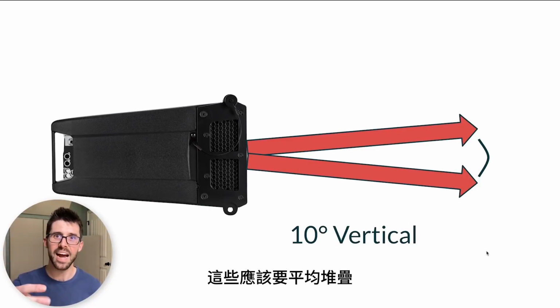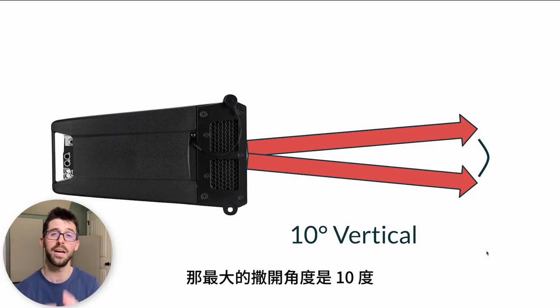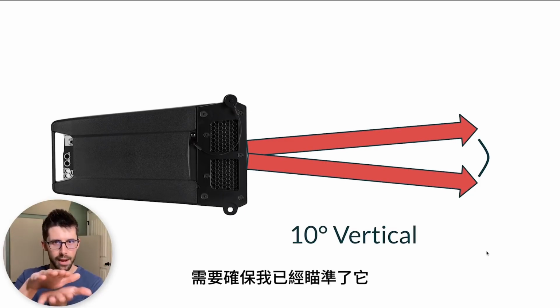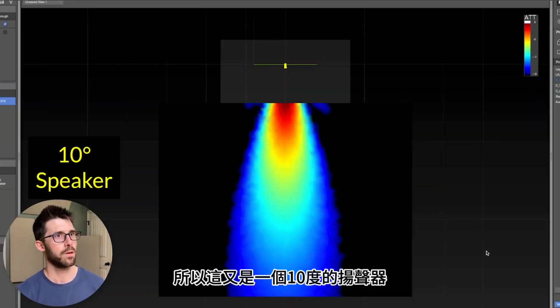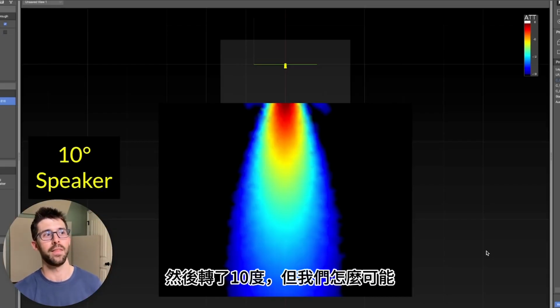So these are meant to be stacked up in a big long line, and you can vary the coverage angles between them. Its maximum splay is 10 degrees, or it can be used on its own as a front fill. If it's on the edge of my stage, I need to make sure I have it aimed right at people's heads, because 10 degrees is not a whole lot of wiggle room, right? So this is, again, a 10-degree speaker, really tight. See a huge difference between 100 degrees right here and then 10 degrees.